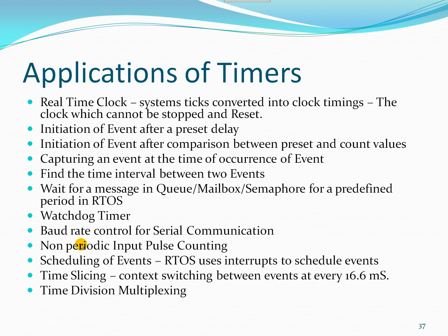Based upon the prescale and postscale values we tune for the serial communication, that is, upon tuning the baud rate of the system, we will give that tuning to the timer. So this is one of the great applications for serial communication purposes.